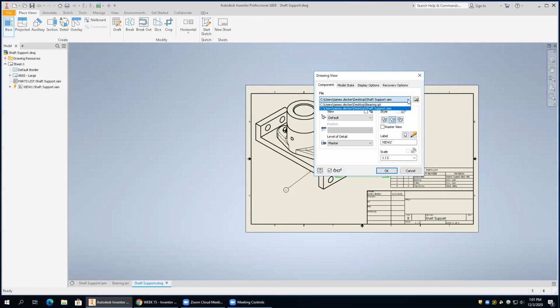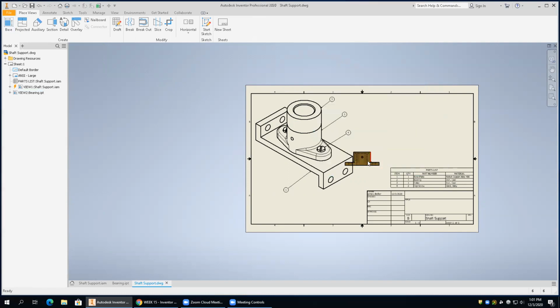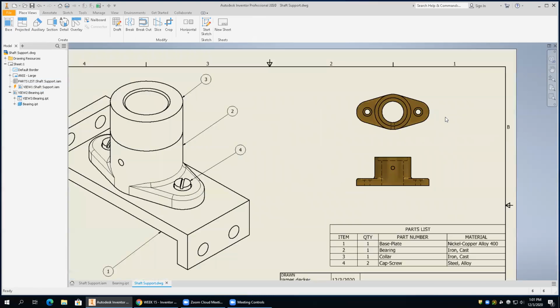and I find the drawing that I want to place the base on. So for instance, I would have to open this up and go to where my part is. So I have a bearing right there. Bring that guy in. I could bring that part right there. And then I could bring a projected view on the top and then create those two views. Those guys can be brought in separately. Okay. And then those could also then be annotated with dimensions and those kind of things. So on a small drawing, this wouldn't make that much sense, but in this one, it's not bad. Okay, you guys get the idea?